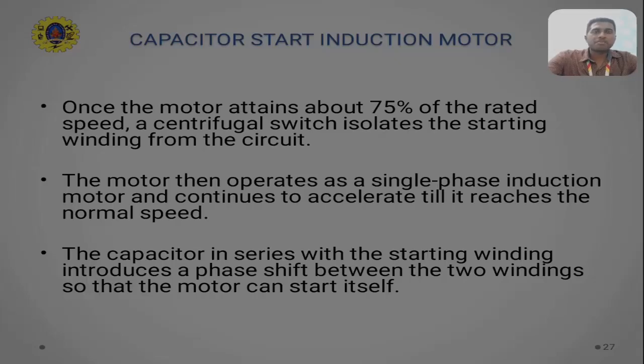Then the motor operates as a single phase induction motor and continues to accelerate till it reaches its normal speed. As I said, the capacitor in series creates the phase shift between the two windings. This phase shift will enable the motor to self-start.